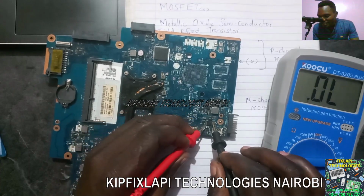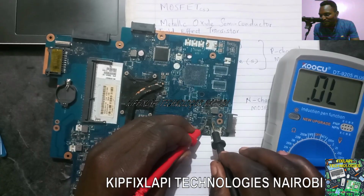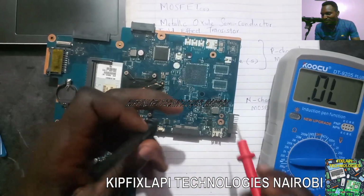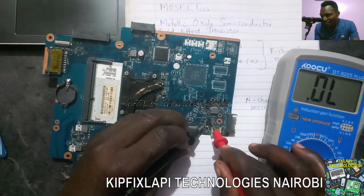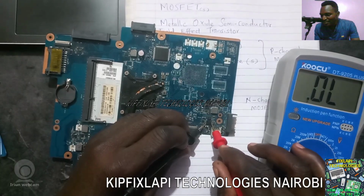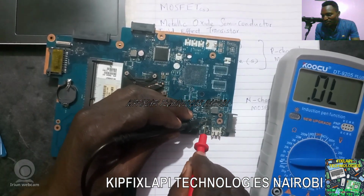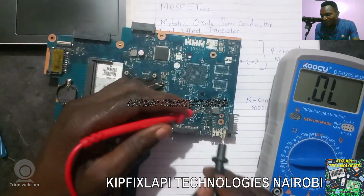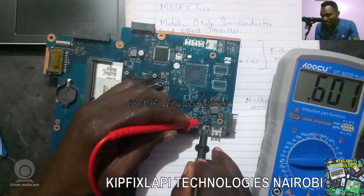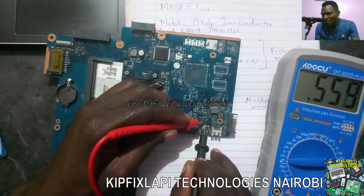Same case, I can test with the gate to the drain. Still, I don't have a problem, even if I interchange the probes, the gate and the drain. Right, guys? Yes. What about the source and the gate? The source and the gate, nothing. Even if you interchange the probes, the source and the gate, you see the resistance? Yes. So that component is good.